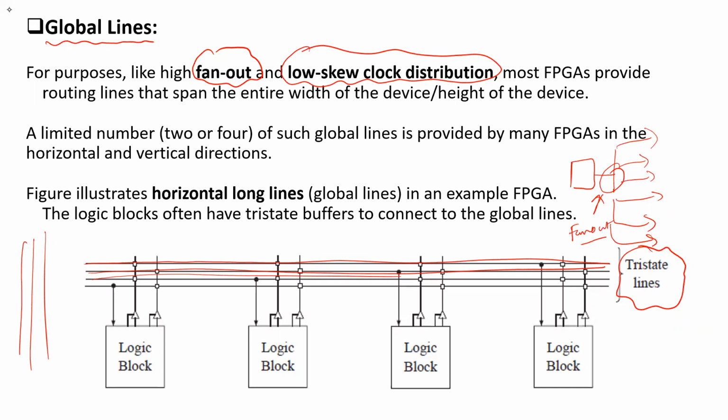So in that sense, depending upon your application or what kind of FPGA you are using, they will already intimate to you what kind of interconnects they have used, whether global interconnects, or maybe direct interconnects, or switch matrix based interconnects. Sometimes they will use all these three interconnects depending upon the resources they have available in an FPGA.